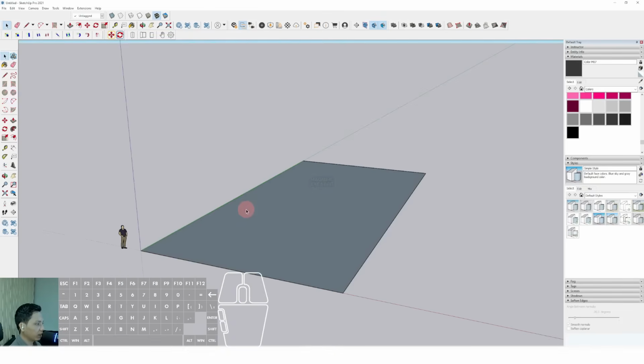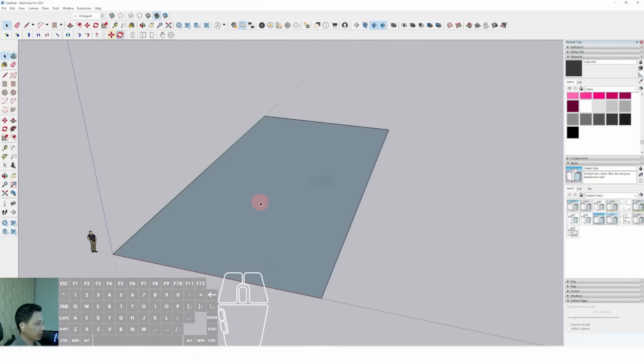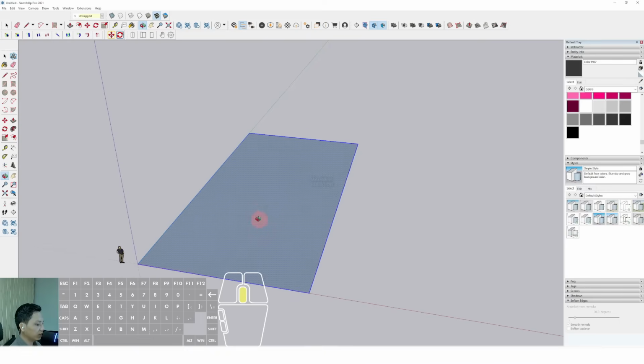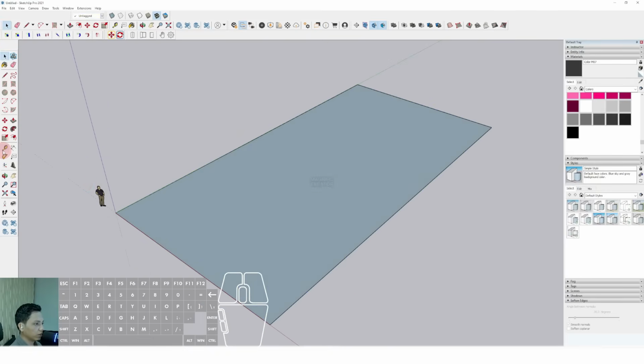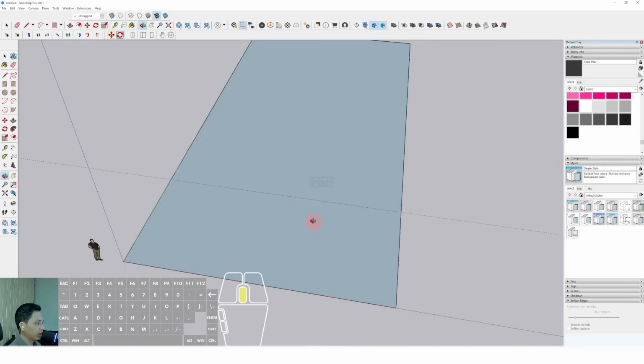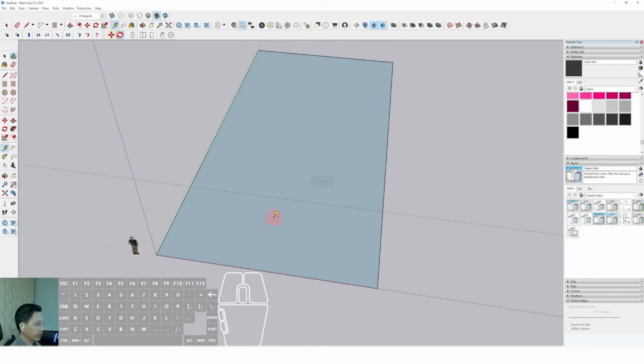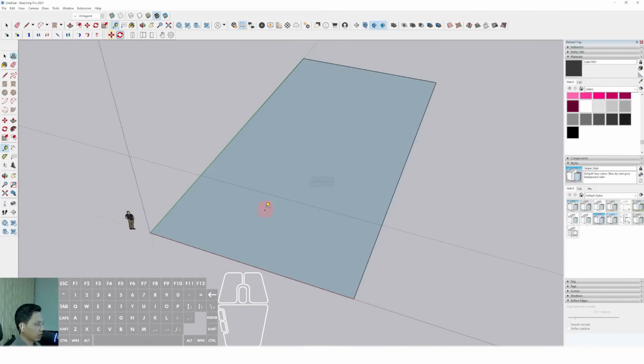With the interiors. Then we can triple click this one and use the tape measure tool, click from this edge to behind, and set 7 meters, because we have to prepare this for the car garage or carport.